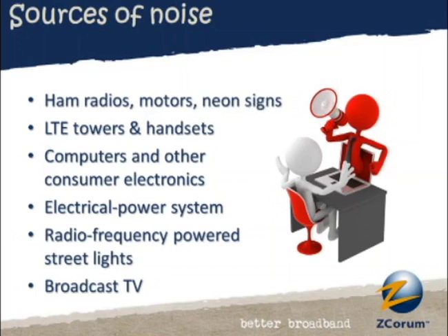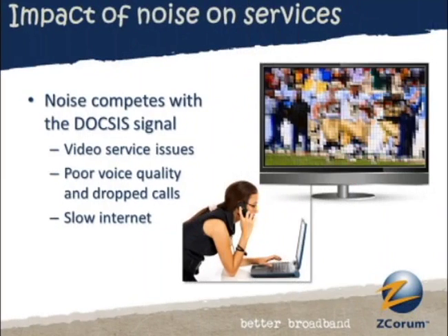It's very possible for RF frequency to shift so that a frequency that's not in use on the cable plant that's in the air can get shifted by either a reflector or another source of interference, so that it is something that interferes with one of the bands that we use. Okay, and once there's noise in the plant, it's going to have an impact on the operator's service.